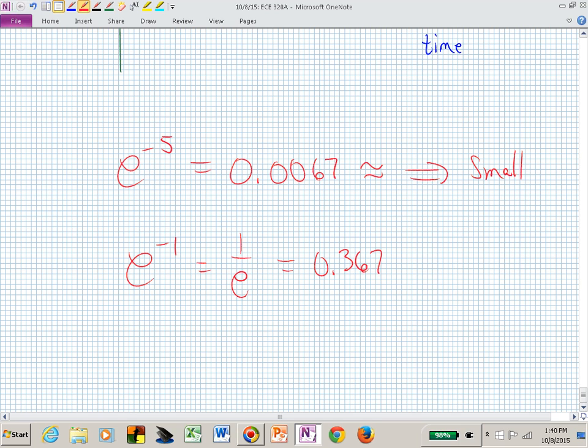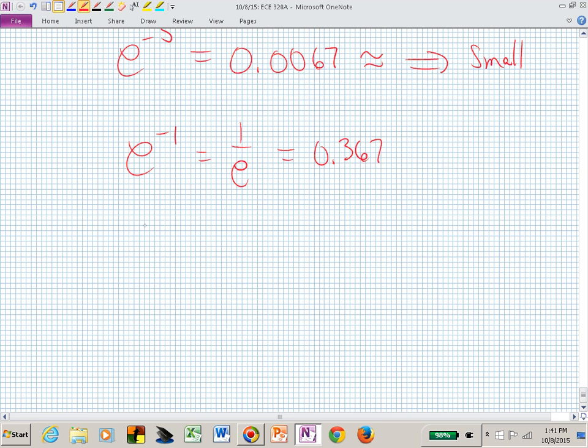And now I know you're going to run home and just be going e to the minus 2, e to the minus 3, e to the minus 4. E to the minus 4 is 4 time constants, and that's 2%. And in a controls class, a lot of times you play with, what's my 2% settling time? What happens in 4 time constants?